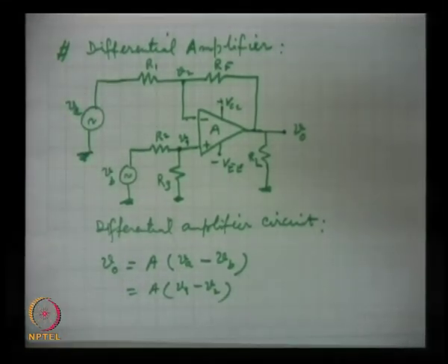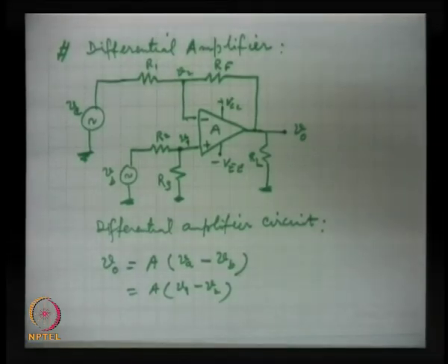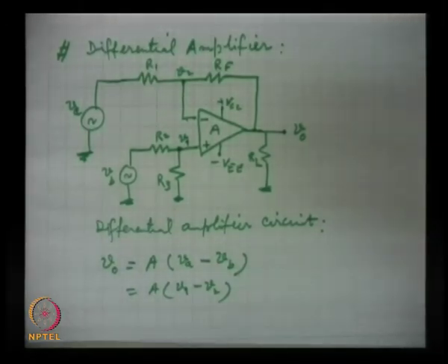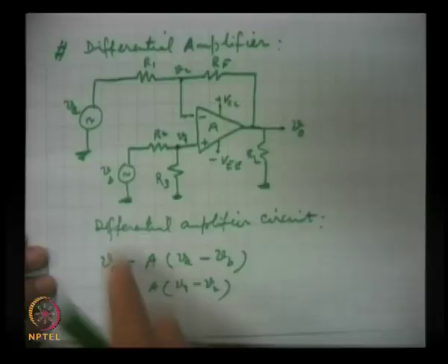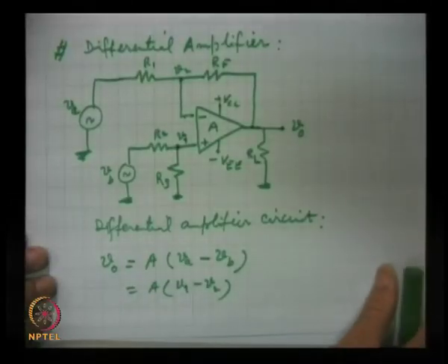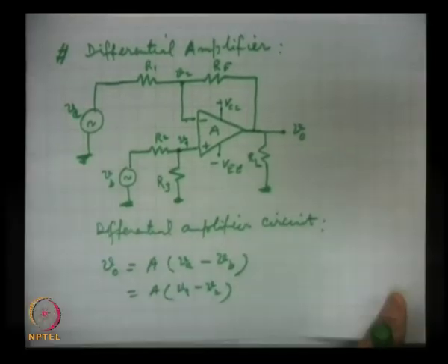Again we will take the output, and the net output, by the superposition theorem, will be the algebraic sum of the two, the net output of the differential amplifier. So, remembering this design, which we will of course need in our discussion further, the relationship between input and output voltages can be obtained.